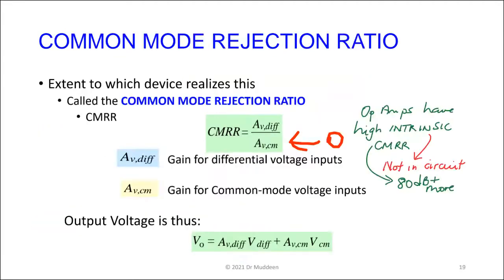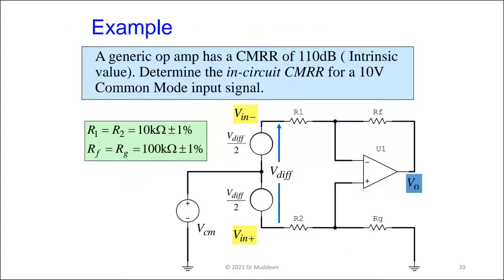But as we will see, and we'll do this example tomorrow, resistors have a tolerance. The ones that you have in your kit have a tolerance of like what? 1%, 5%, 10%? If you're not sure about it, you have to look at the color band on it. Some are 5%, some may be 10%. I don't think any of you have 1% resistors, but the kit may have a combination of 5 and 10%. What we're going to look at tomorrow, you could read ahead on the slides this afternoon if you like, or later on, is this.